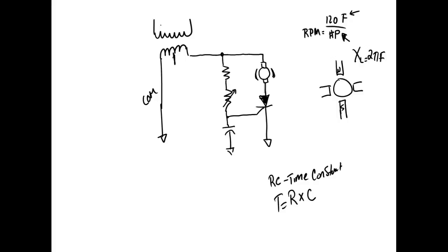So AC motors, we don't control with the frequency by itself. What we do is set up what we call a voltage to hertz ratio. So if I raise the frequency, I raise the voltage by the same percentage, right? You understand? And if I lower the frequency, I lower the voltage. So that's why for years and years and years, if we wanted to control the speed of a motor, they were DC motors.